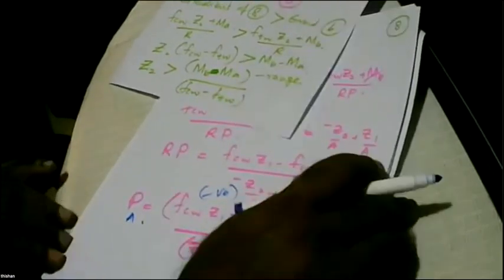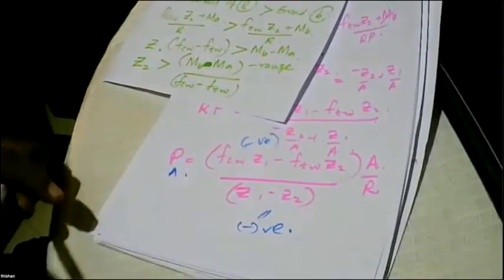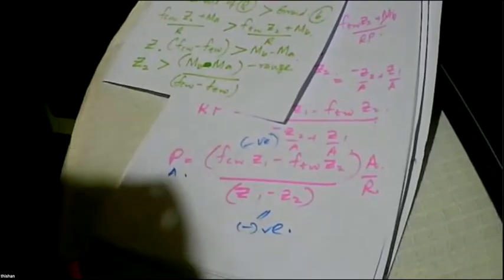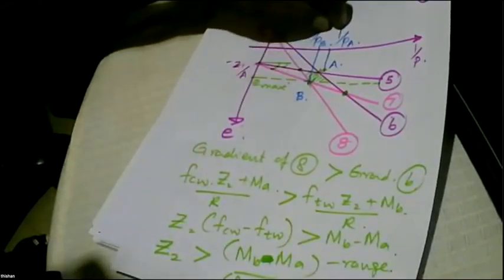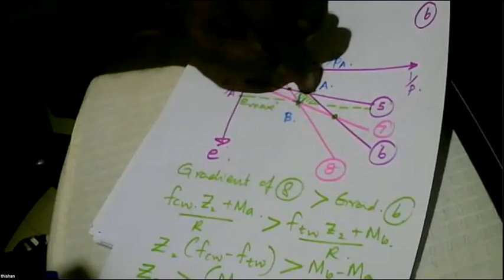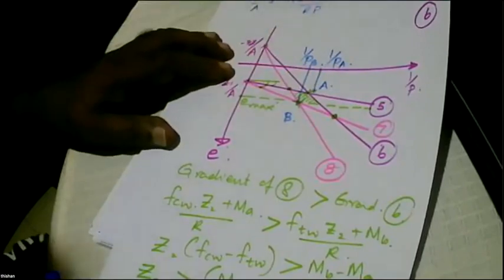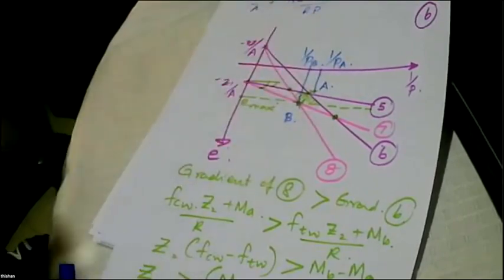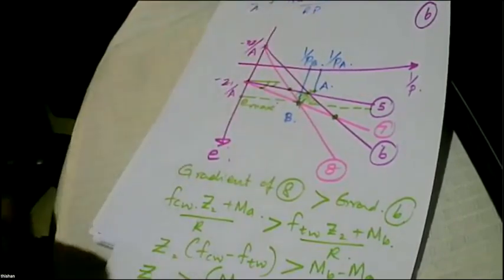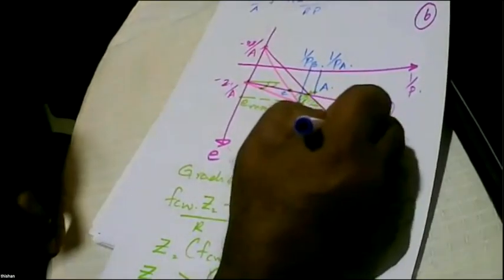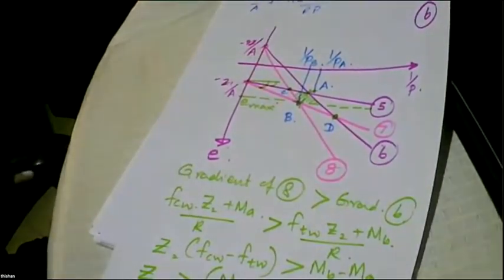But now let's look at what are the important things. Now, does this point depend on section sizes or the bending moment? It doesn't depend on the bending moment. So that means along the beam, the Magnel diagram will move like this in a narrow band. This PA and PB will be independent of the bending moment, whereas these points will be dependent on the bending moment. We call them C and D. C and D will be dependent on the bending moment. A and B will be independent.